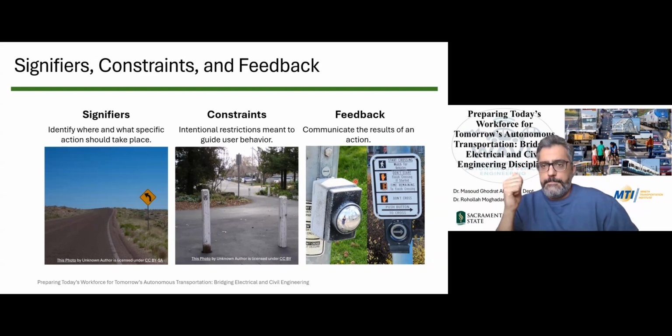First of all, sometimes your experience or your understanding of a system might not be exactly what is going to happen next in using that system. Look at this roadway. You're driving, and this is going up. This is what we call a vertical alignment, but there happened to be also a horizontal curve right at the top of this vertical curve. So I have no idea how sharp this turn could be.